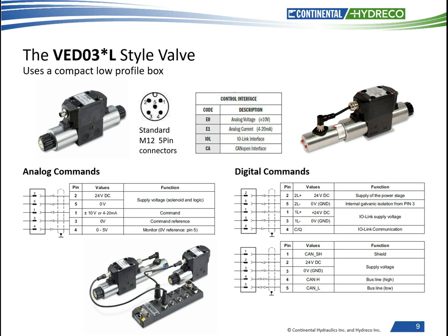The new design electronics also allows for additional ways to control and connect to the valve. The standard uses an analog input, plus or minus 10 or 4 to 20 milliamp. This option also brings in a digital control, making it very easy to implement. Here you can get the IO-Link communication protocol, or you can get CANopen communication. These new control options put you in the driver's seat, as most of our competitors don't offer controls like this.